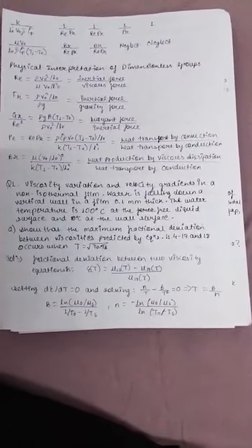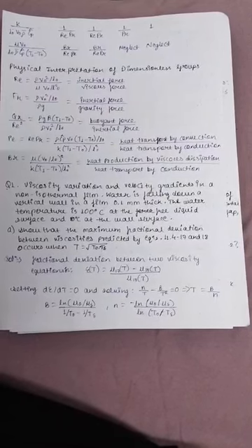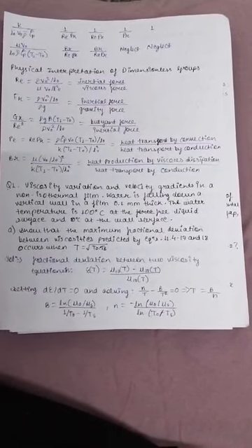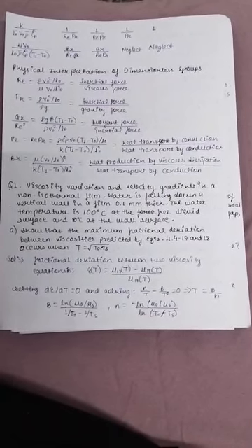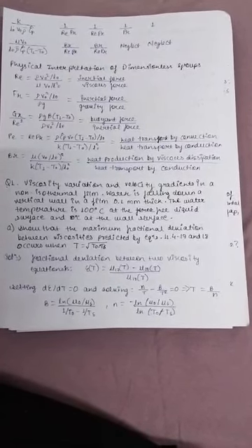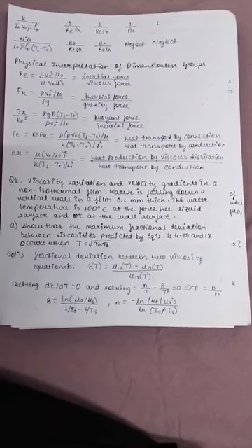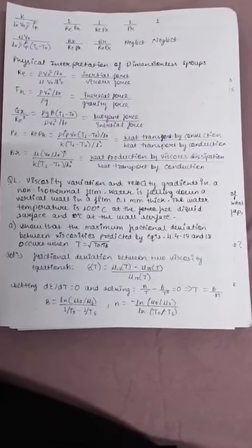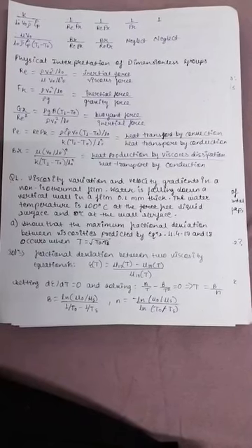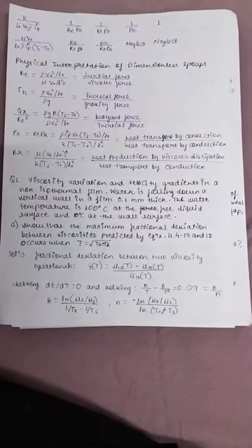Now let me continue with the table of dimensionless groups and then give their physical interpretation. K over L naught V naught rho Cp hat equals 1 over Re times Pr for forced convection, 1 over Re times Pr for intermediate, 1 over Pr for free convection A, and 1 for free convection B. Mu V naught over L naught rho Cp hat (T1 minus T naught) equals Br over Re times Pr for forced convection, Br over Re times Pr for intermediate, and neglect for free convection cases.